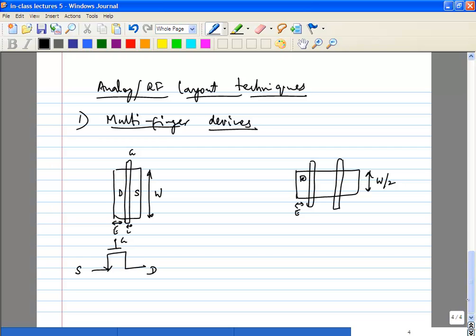Those are all things which are very important, and there may be cases where you really want to widen out this E, because if the transistor is operating at a very high current density, you might want to have a wider contact region and more number of contacts. By the way, contacts also have current density requirements. So you may want to have more contacts in some cases, but in most cases, let's say we'll just consider.